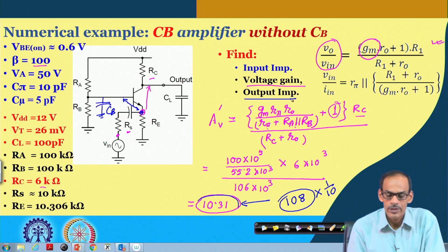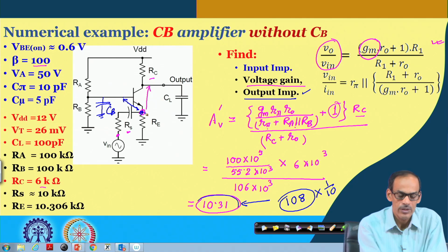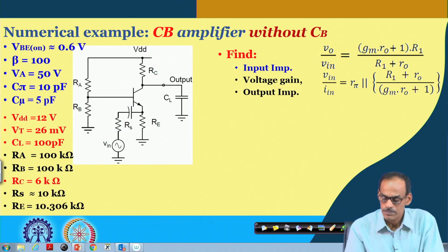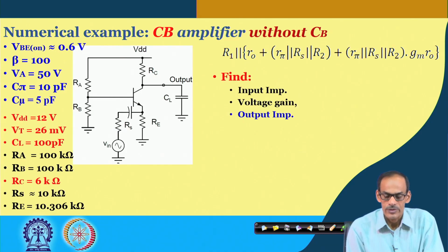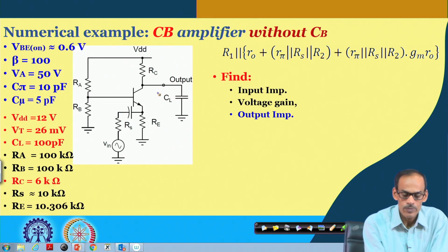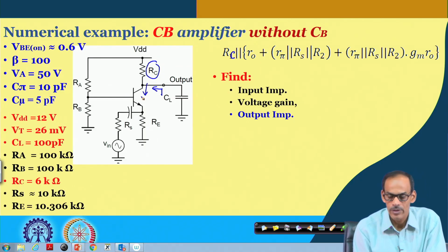So, similar to the input resistance and voltage gain, the output resistance is also getting affected, because the resistance at the emitter is getting changed if we remove this Cb. So, this is the slide to get the corresponding derivation of the R out, the output impedance for this circuit. It is this Rc, I should write here, Rc in parallel with whatever resistance we do have.